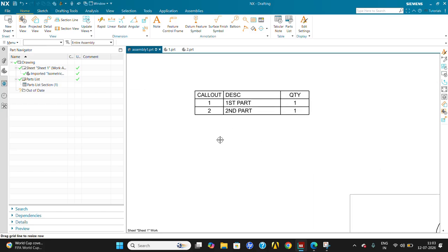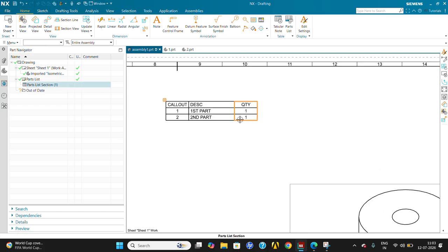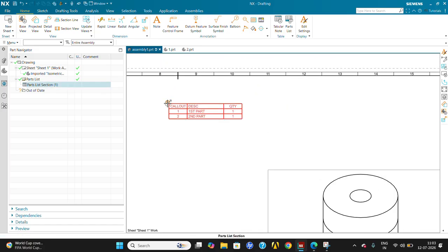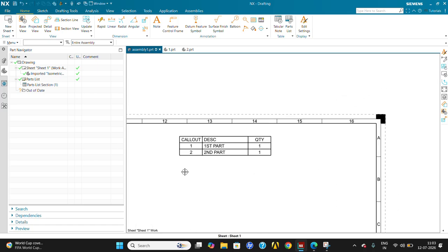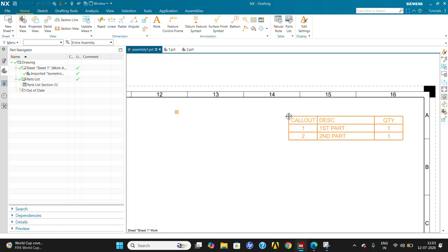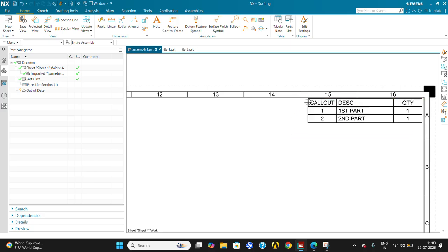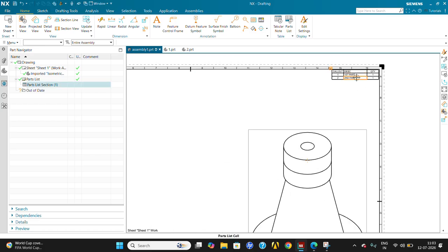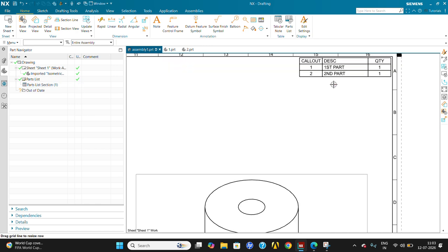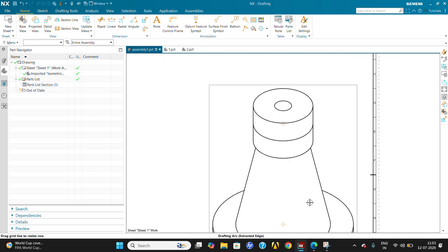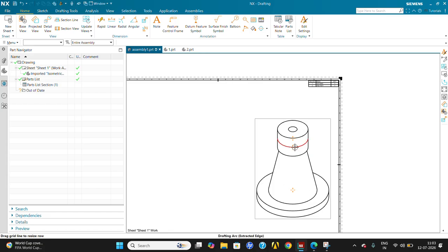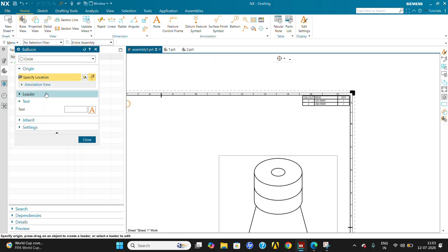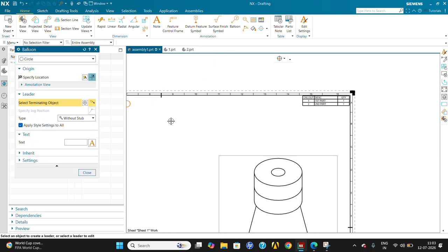This is the method of how to create the BOM in Siemens NX. I hope you got it. It is by using the output, by giving the attribute, how to create the BOM in Siemens NX for all the parts. So now we created the BOM. If this BOM is linked with this body, automatically the BOM will also update. Give the BOM and that.